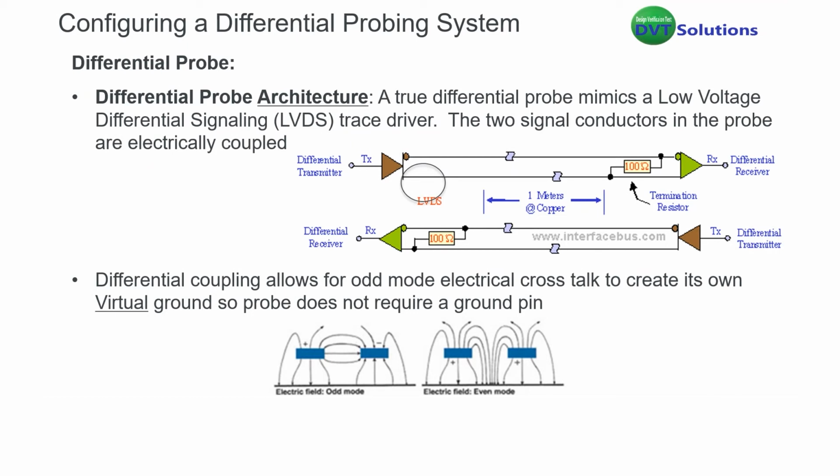So, differential probe. We developed the first true differential probe back in around 2005 when the LVDS circuits started to come out from National Semiconductor and a few other companies. This changed the entire architecture at that time from point to point to a dual line differential interface. And it was designed so that you're able to reject common mode noise. So a power supply glitch, if it occurred, wouldn't just wipe out your data and your system crashes. It also allowed you to use a lower voltage to define the ones and zeros so that you can move data faster down a transmission line.